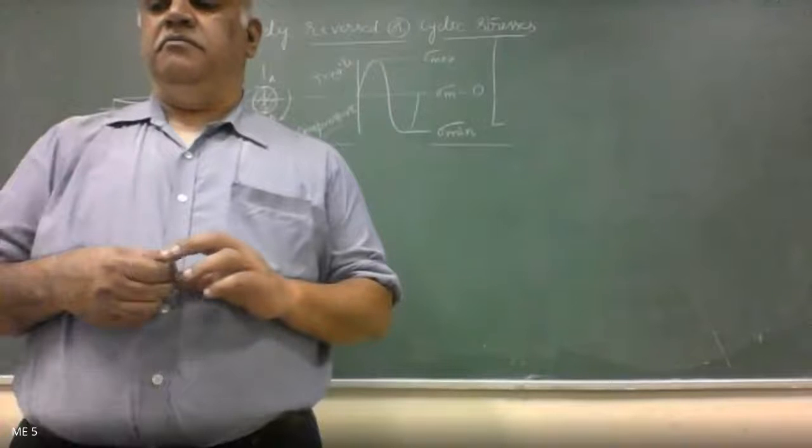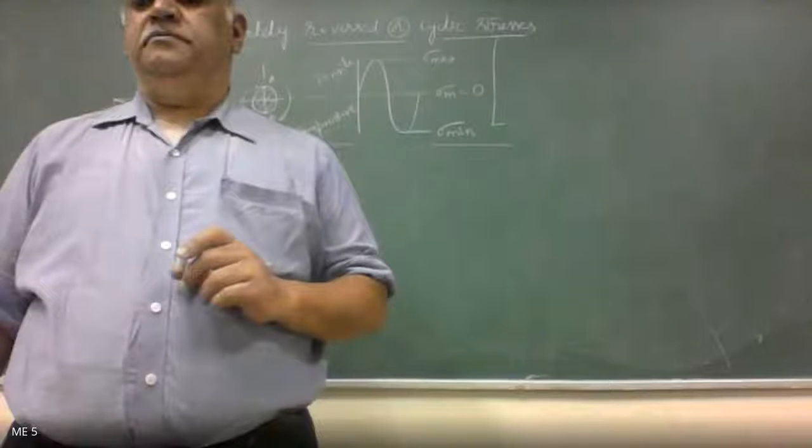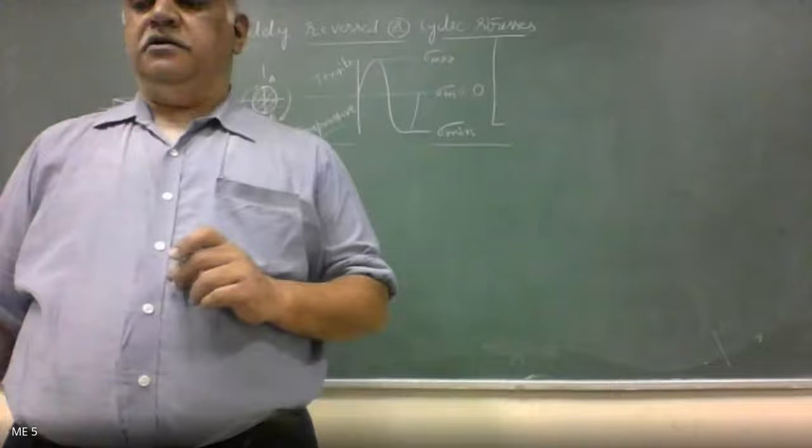The maximum pressure in the cylinder of a double acting type is 0.9 megapascal. Okay. The bore of a cylinder is 500 millimeter in dia. What should be the diameter of the piston rod if there are no stress risers and column actions? Correct.